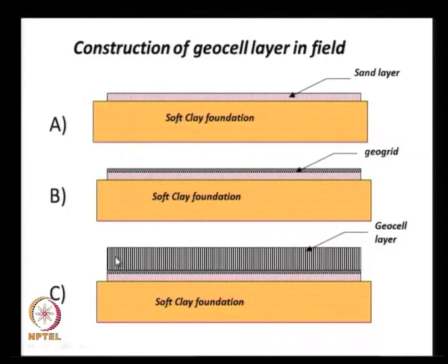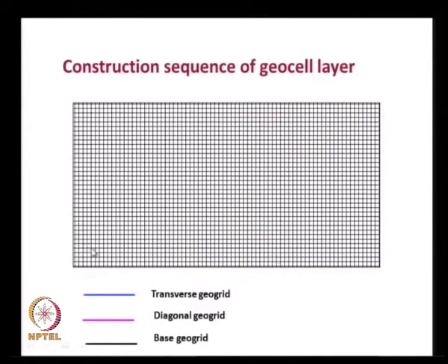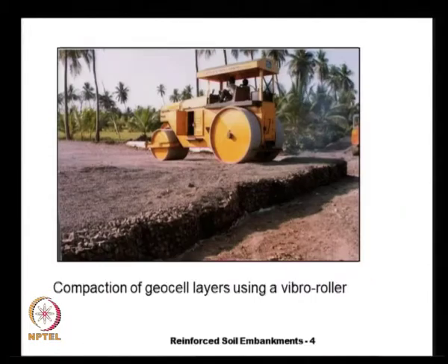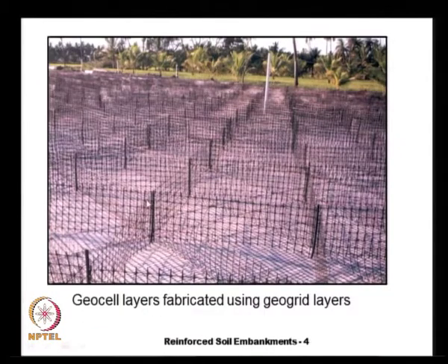And then we construct these geocell layers, vertical geogrid layers. The procedure is something like this. This is a plan view. We lay the geogrid separator on the ground, and then we have these transverse geogrid layers that are constructed, and for this purpose we need to provide some supports along the length, like what we see here. These are called Bodkin joints, and they also provide some vertical support for the formation of this geocell.